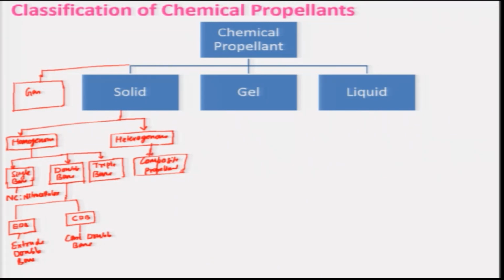And keep in mind that again you can have extruded composite propellant, and then also you can combine this double base and composite propellant, which is known as combined composite propellant. Various kinds of permutation combination one can have. If you consider heterogeneous propellant, it undergoes a pre-mix combustion type, and in composite both the pre-mix and diffusion flame based combustion will be taking place.